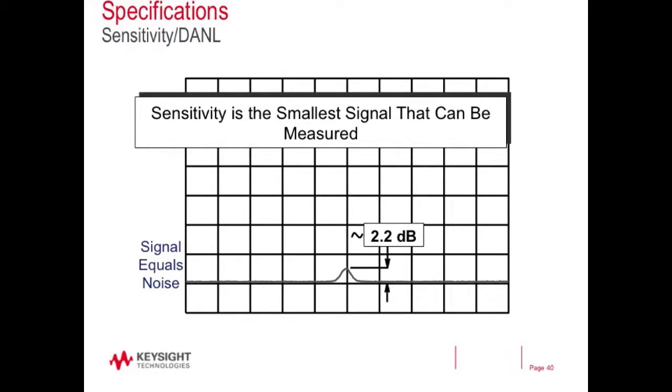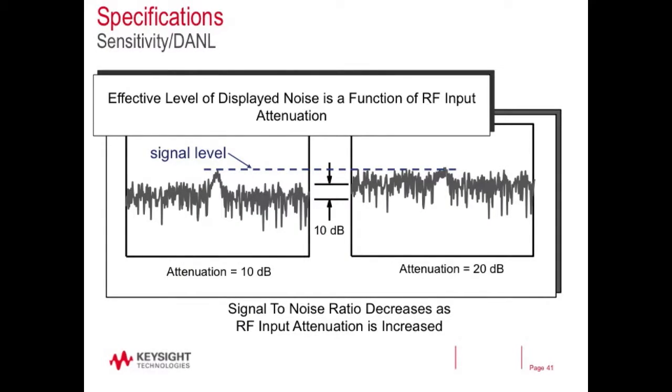So this is important, right? And again, the better your signal analyzer, the lower the noise floor. And depending on what industry you're in, some people operate near kTB, right? And they're trying to find spurs or unwanted signals way down there. And so that's what displayed average noise level is all about. So you as a user can essentially impact the displayed average noise level that you see on the screen, okay?